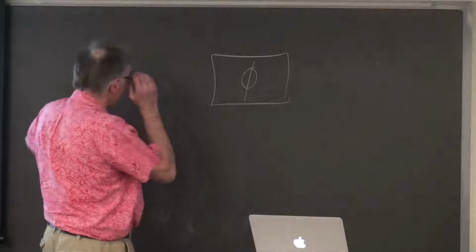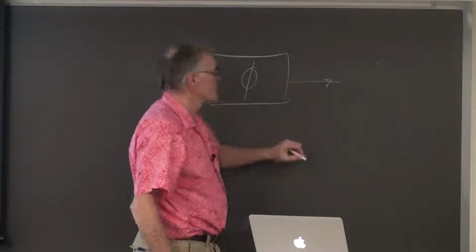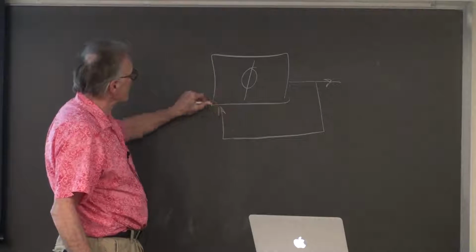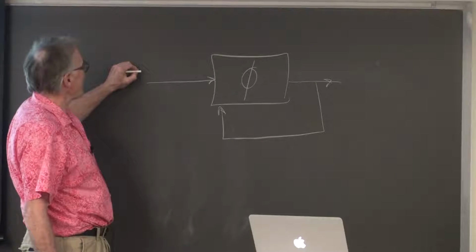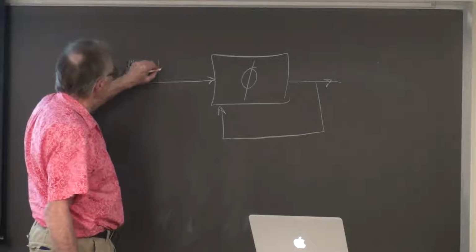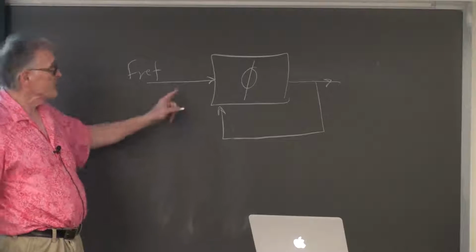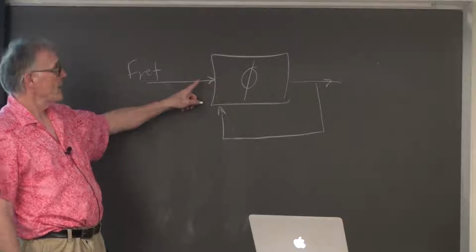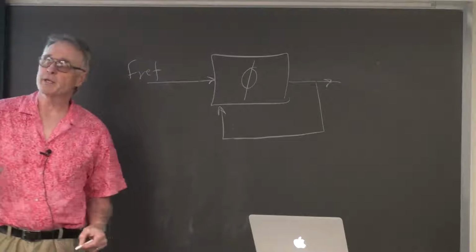And the basic operation is that there's going to be an output square wave that is fed back into here and compared in phase to an input F reference frequency. So if you phase lock these two, then this output will be at constant phase relationship to F ref in, so they will be at the same frequency.